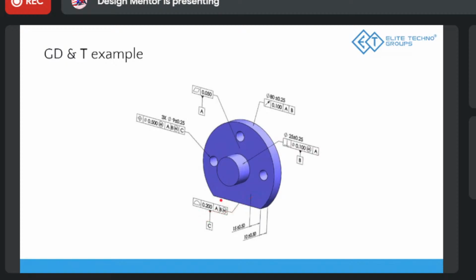So here also we can see the dimensions are already given, and we need the profile of the surface. As I told you, if it's a curved surface or some bends are there, we again put two lines around that surface, and it should land between them. If it's going above or below that imaginary line, it's not right.